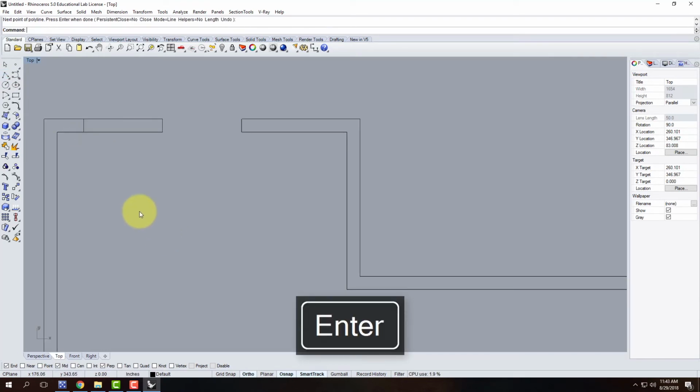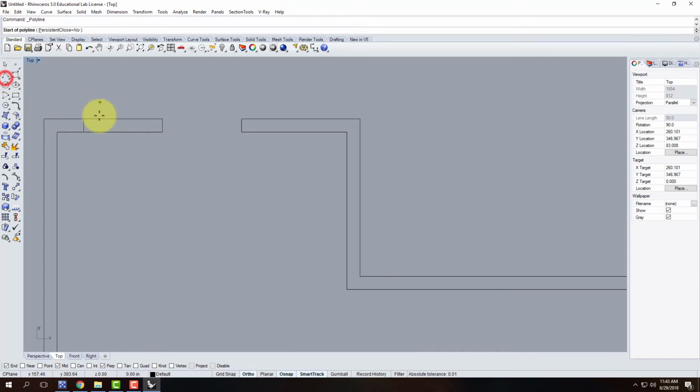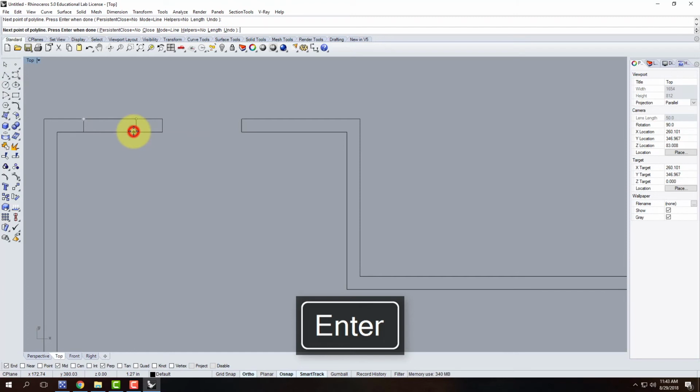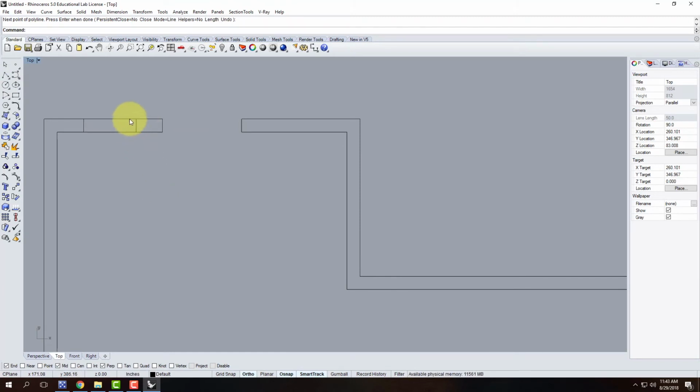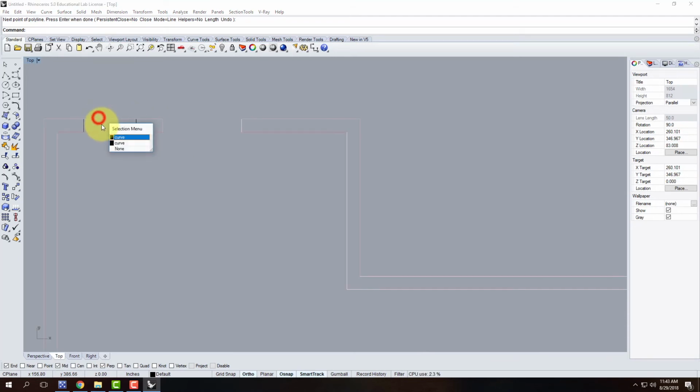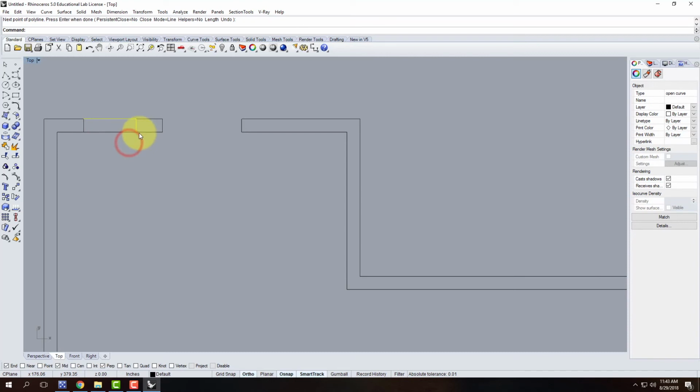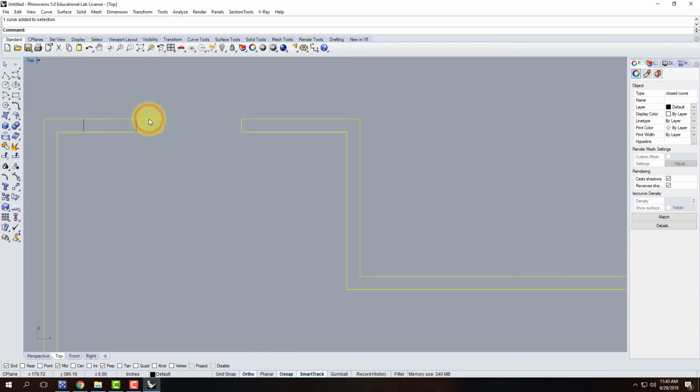I've got the side of my window, that's great. Oh, the other side, this is 2 feet over, let me just go 2 feet, and then I'll draw down, perfect. And I have my window. The problem with that is you created not just the lines here, but you created lines that are on top of each other. See how this is an L-shaped line? This line is on top of that line. And when you go to make the object three-dimensional, that's problematic. So we don't want to have that happen.